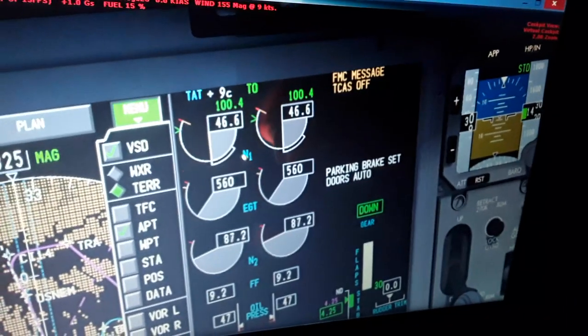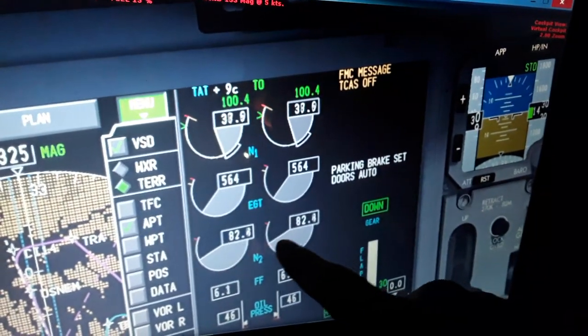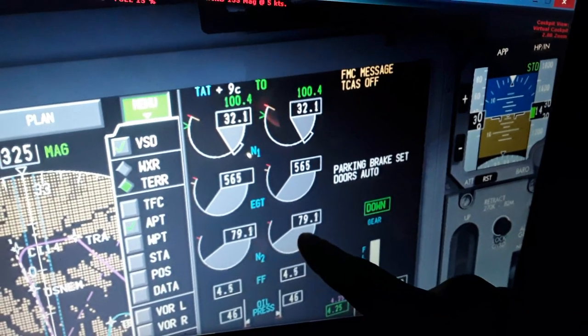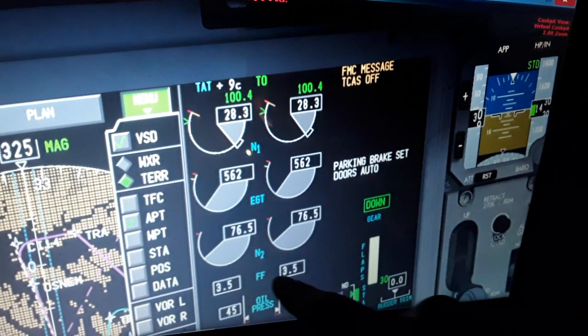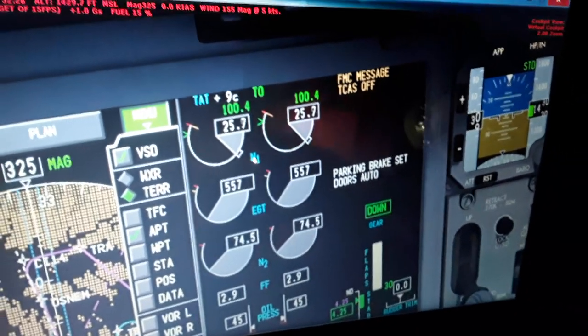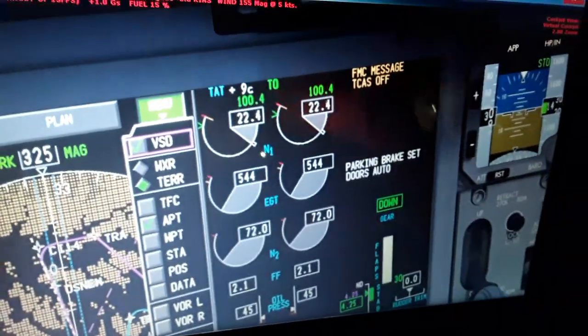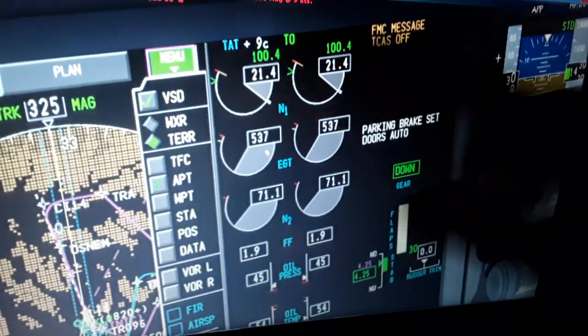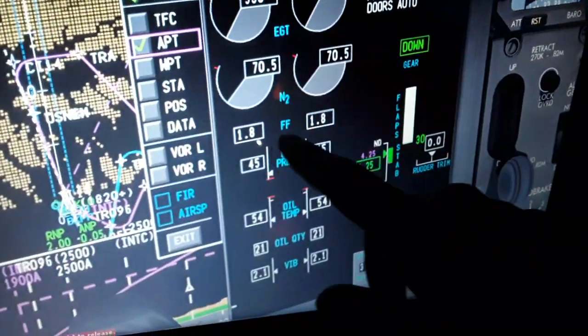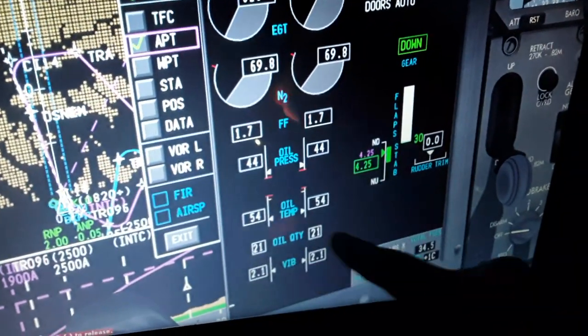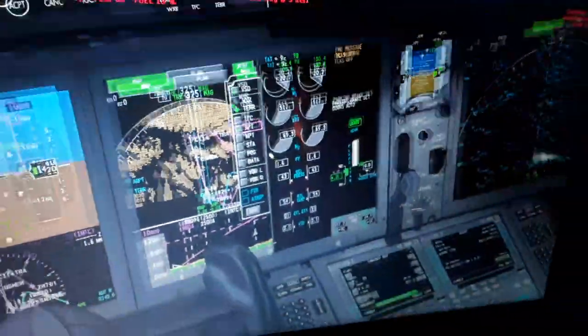The red warnings. So this is the high speed shaft, the high pressure compressor turbine of the turbofan turbojet engine, and the fuel flow per engine per hour, in 1000 kilograms or 1000 pounds. You can see red, green, yellow limits not to exceed, takeoff, total air temperature, fuel flow per engine per hour, oil pressure, oil temperature, quantity, and vibration of the N2 stage of the engine.